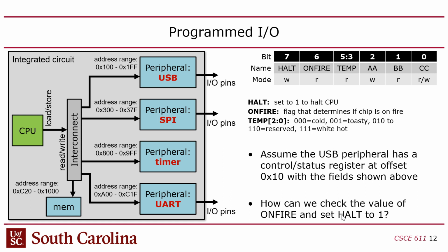Okay, so then these control and status registers are often split up into bit ranges, because a lot of the signals that you want to send to hardware or receive from hardware might just be 1 bit or a few bits. So generally they'll pack these bit fields into these control and status registers. When you access them from software, you have to extract the bits you want or insert the bits you want, so you have to do bit manipulation.